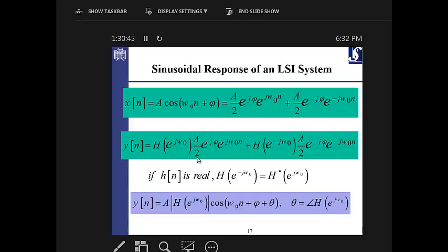You don't care about the constant in linear transforms. It just comes outside. On the other hand, e to the power of j phi is also constant, because phi is constant. It comes out. These are constants. You don't care about that. But this part is a basis function, an eigenfunction. So whatever the output is should be a weighted, scaled version of the eigenfunction. We already saw that. The same thing happens for the other term. And I already said that, based on the Fourier theorem, every signal in the time domain can be represented as a superposition of these eigenfunctions.